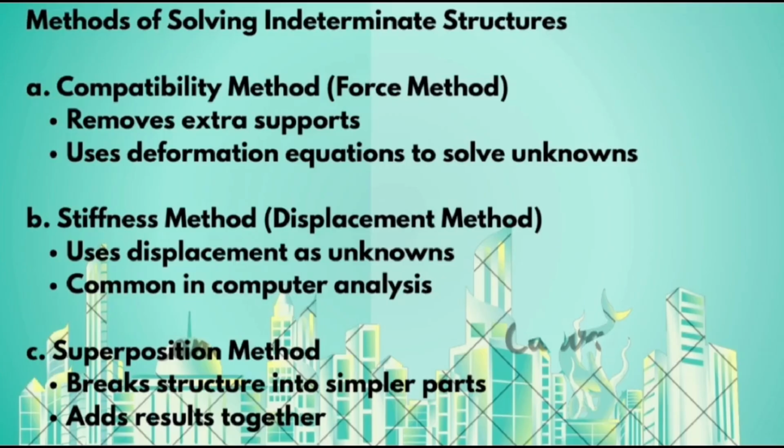Next is the stiffness method, also known as the displacement method. This uses displacement as unknowns. So you are looking for displacement. This is much more common in computer analysis. Last is the superposition method. This breaks the structure into simpler parts and adds the results together.